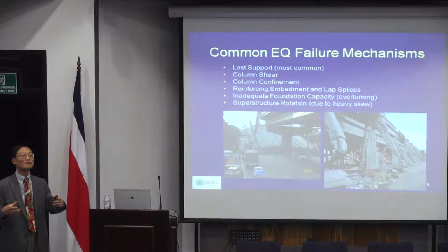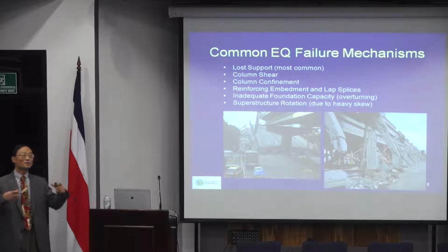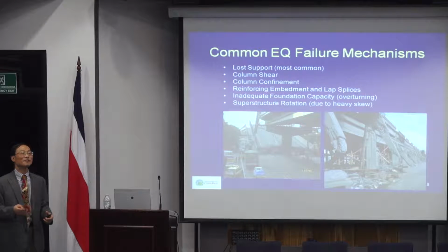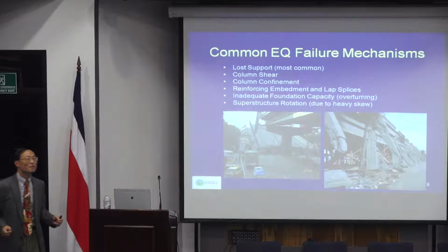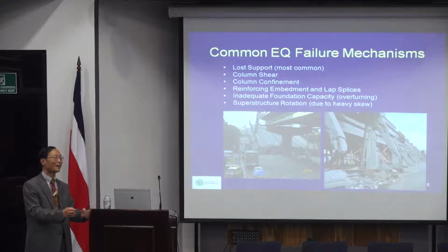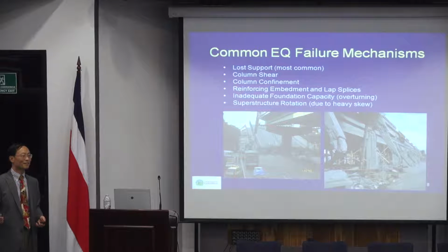A very small column will be sufficient to carry this load. If you have lateral load, people will typically at least design for what we call longitudinal force. In other words, when a truck suddenly brakes, there will be an inertial force pushing the deck, or the wind load. But these are usually not very large.